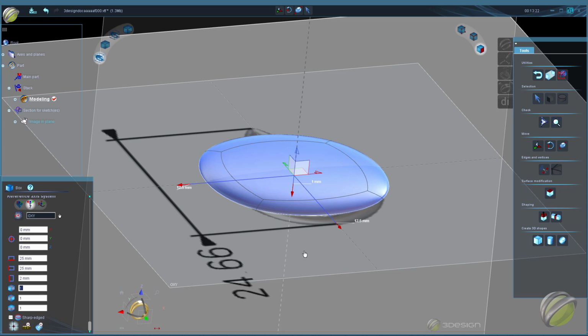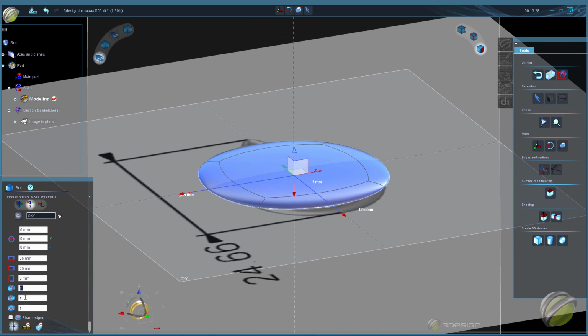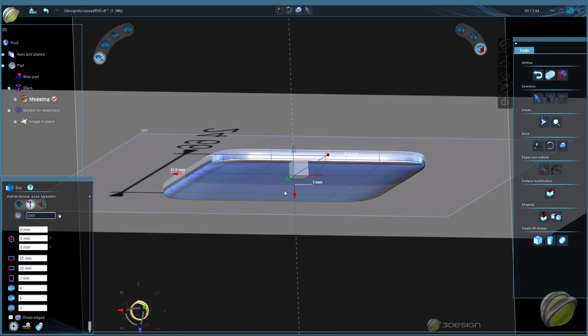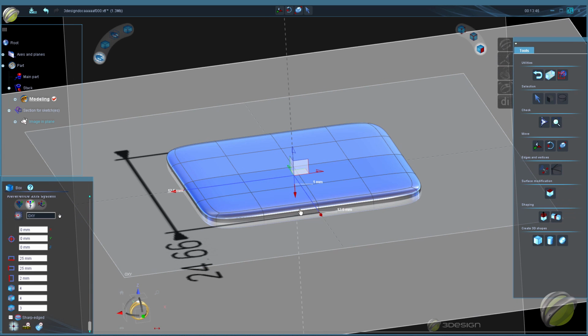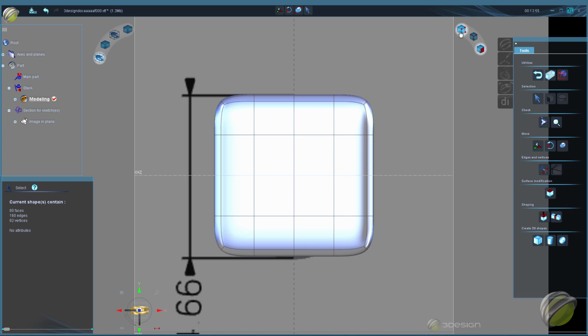And then we have to choose the number of subdivisions. Right now when we build it that way, we get this flat little disc and not a box at all. So if we subdivide that, I'm going to do 4 and 3. So 4 across the top in both directions and 3 across the sides. Now we see we got more of this flattened out box. So that's all set up. We'll go ahead and jump to our editing tool, and we're going to switch to the vertex mode or the point mode so we can select the points and start shaping them.